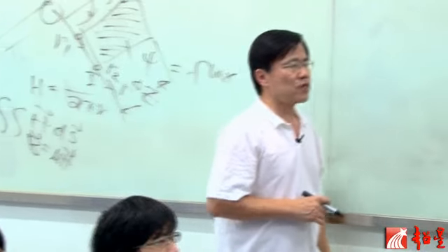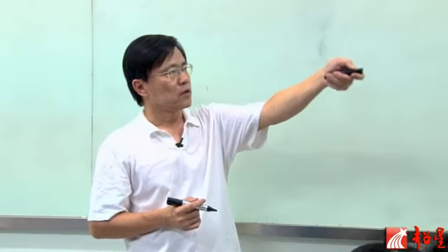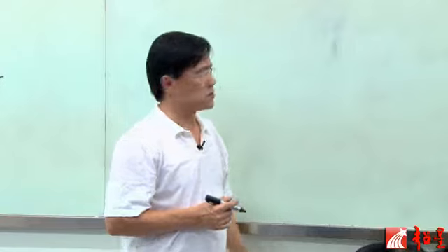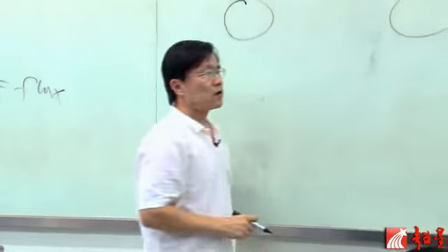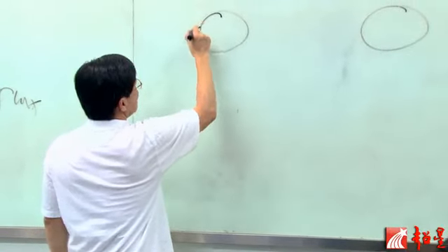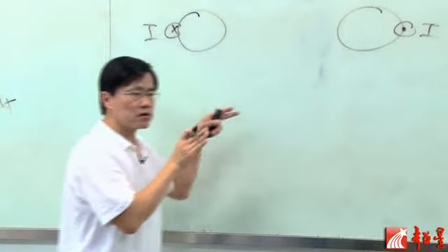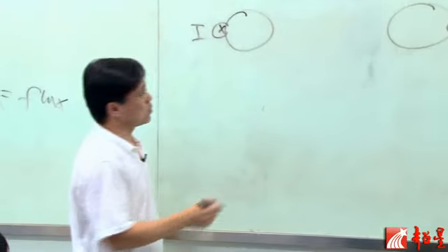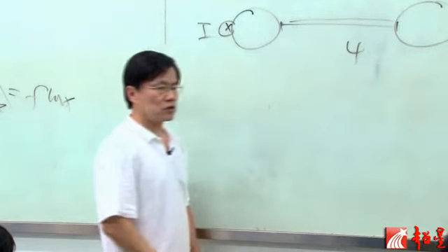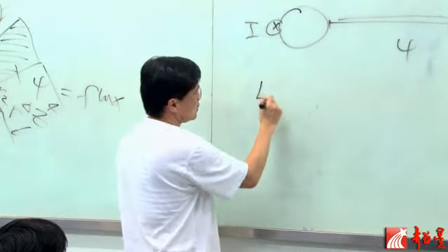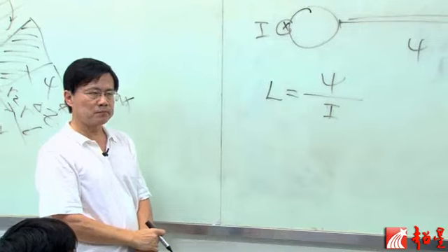All right? Now, if I need to find out the inductance between these two wires, okay? So I have one wire here, one wire here. For the inductance between two wires, I have a current that goes into this wire and comes out of this wire, right? The same current goes into this wire, comes out this wire. And this is the area of flux I'm interested in, okay? Because inductance is defined as flux over current, okay?